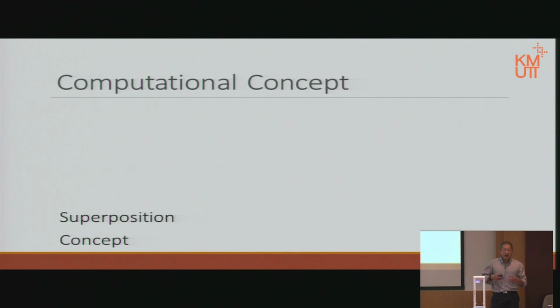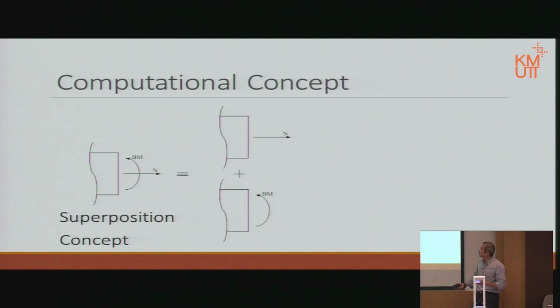The underlying theory is what we call the superposition concept. We talked about the superposition concept already when we did the force method for the axial force. The same idea applies here. If on this cut section we have axial force and bending moment applied on that cut cross section area, because we know that the distributions are different, we don't know how to calculate them together. So what we do is use separate cases like this.